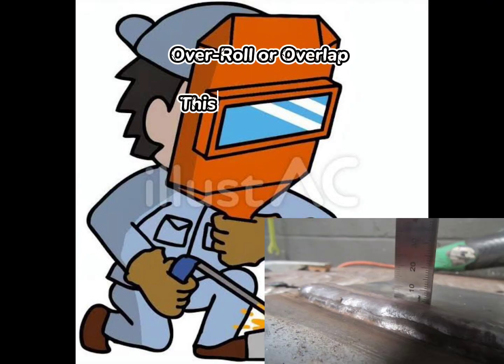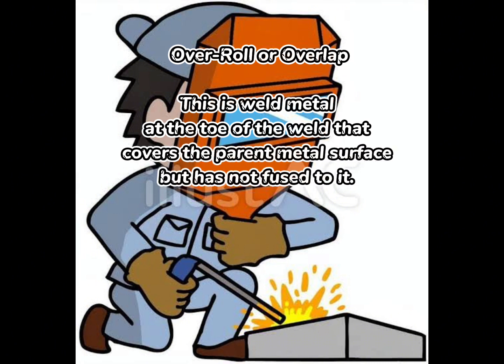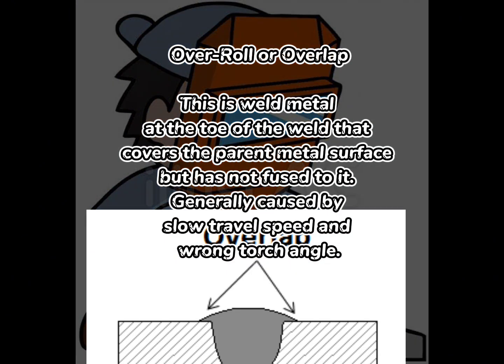Overroll or overlap. This is weld metal at the toe of the weld that covers the parent metal surface but has not fused to it, generally caused by slow travel speed and wrong torch angle.